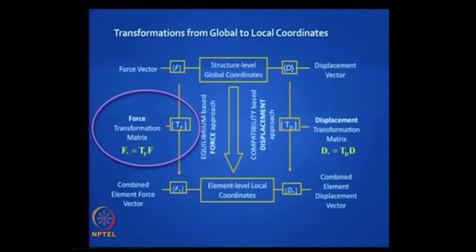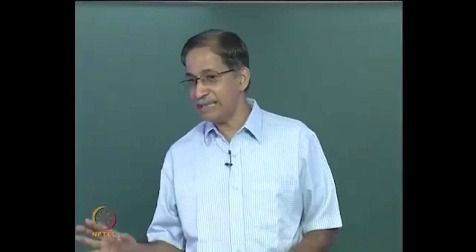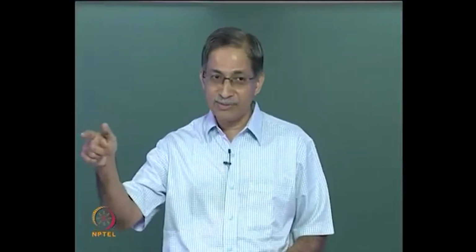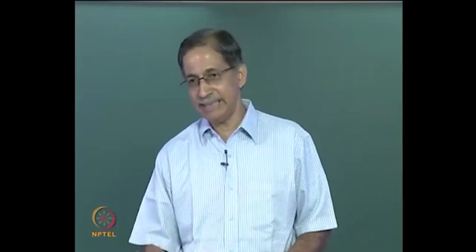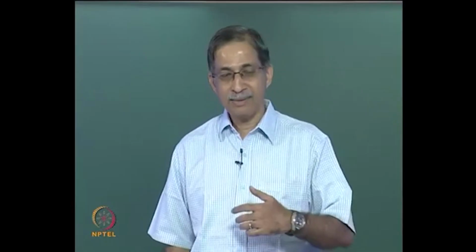So now we are going to look at what one of you asked, can we do this transformation. So this is our TF transformation. Remember we looked at the TD transformation in the stiffness method, both the conventional stiffness method and the reduced stiffness method. Now you do not worry about TD, you look only at TF, and obviously TF must be based on equilibrium alone. So you can uniquely define TF only for a statically determinate structure, because you have a unique statically admissible solution. For a statically indeterminate structure you can't uniquely define TF, please note that.